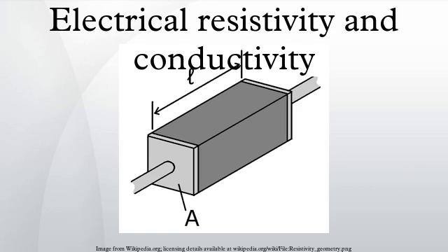As an example, if a 1 m solid cube of material has sheet contacts on two opposite faces, and the resistance between these contacts is 1 ohm, then the resistivity of the material is 1 ohm meter. Electrical conductivity or specific conductance is the reciprocal of electrical resistivity, and measures a material's ability to conduct an electric current. It is commonly represented by the Greek letter sigma, but kappa or gamma are also occasionally used. Its SI unit is siemens per metre and CGSE unit is reciprocal second.